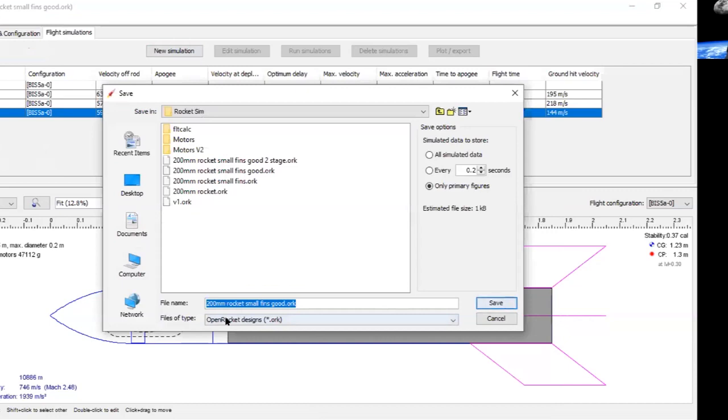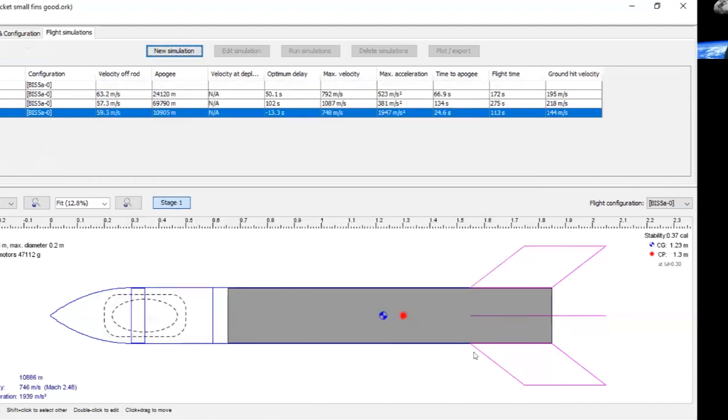You can save it as an OpenRocket file or as a RockSim design. And if you save it as a RockSim design, you can import that directly into RASAero II. And that's a better supersonic model, and it's fully calibrated, and it gives you examples when you download it, of how it's been validated against proper sounding rockets.